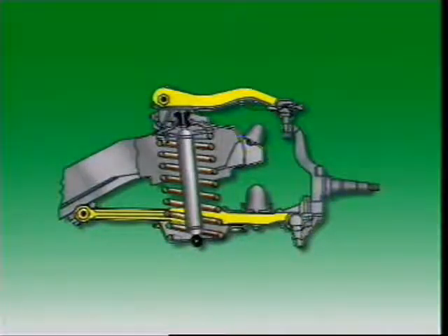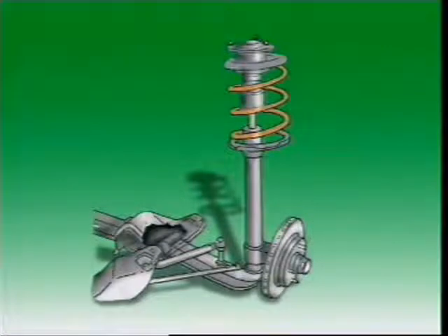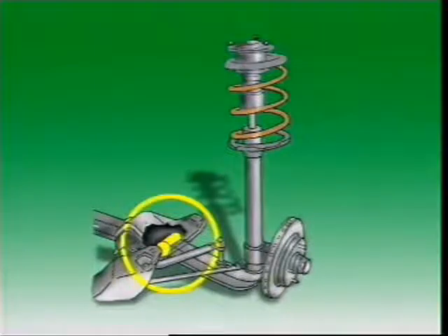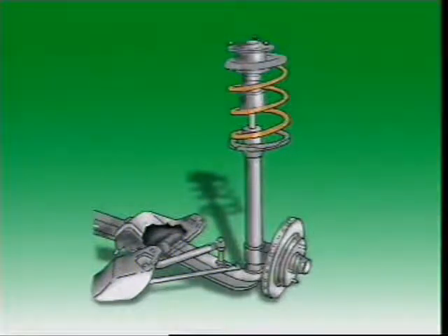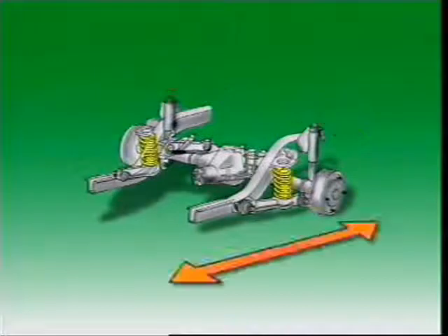Parallel link front suspensions have 2 control arms. Vehicles with strut-type front suspension have only 1 arm. It can be a wishbone shape with 2 fulcrum mounting points, or straight with single fulcrum. The inner end of the control arm is pivoted to the vehicle body, and the outer end uses a ball joint to allow changes in the steering angle for turning. This rear-wheel drive vehicle has coil springs in the rear suspension. Therefore, special provision must be made to locate the axle laterally and longitudinally.